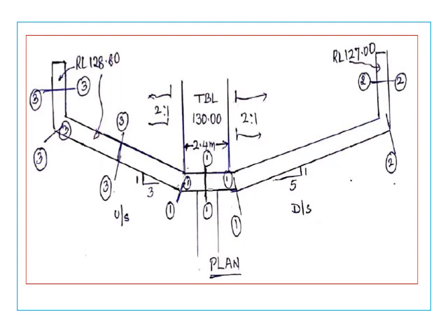Now how to fix the sections? So this is the upstream side, this is the downstream side. We know that for any wall, we call it a return wall, the top should not go below the ground level. We know that the ground level is at 127, so therefore the top of the return is kept at 127. So now the wing wall is sloped from 130 to 127.